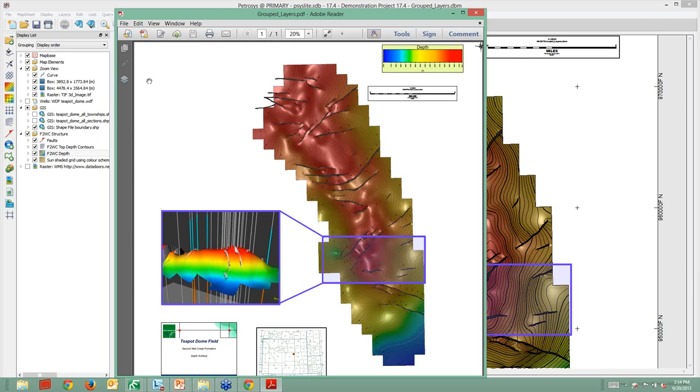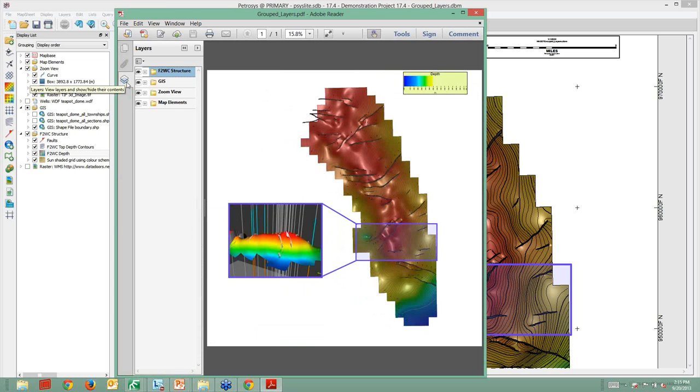We get into gridding and contouring. So again, much easier. You don't have to reformat your stacking velocity ASCII files, or even if you don't have those, you just have it in SegY, we can read that in directly now. Work those into your custom grid arithmetic formats. They're getting saved at the site level.